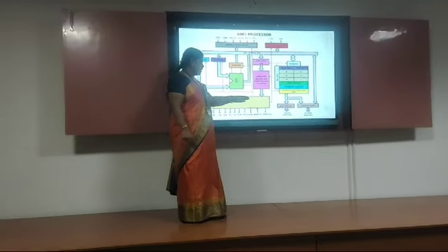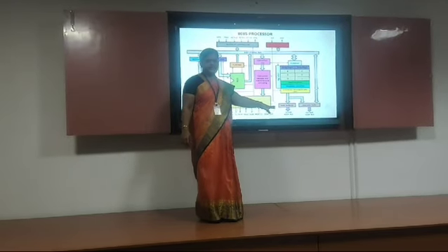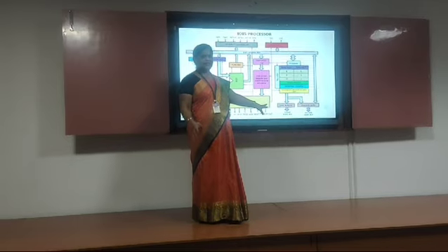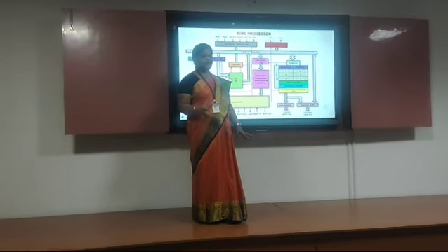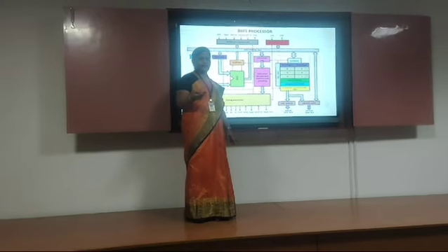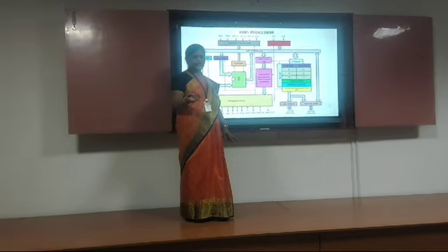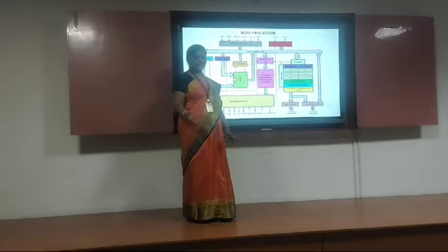When we come to the address and data bus, we have 8 data lines and 16 address lines. What do we mean by buses? A bus is actually a group of wires. It is used for transfer of information. So we can classify the buses into 3 types: address bus, data bus and control bus. The address bus will transfer the address, the data bus will transfer the data, and the control bus will transfer the control signals.